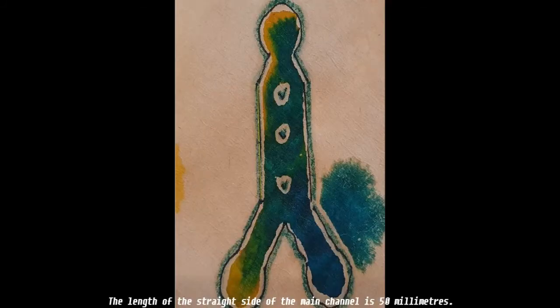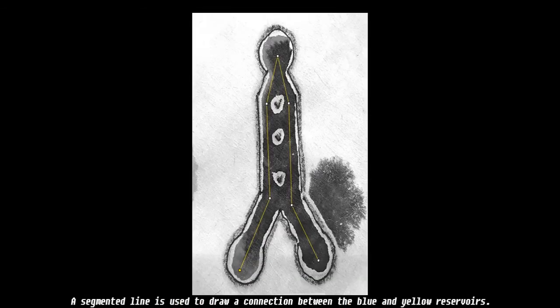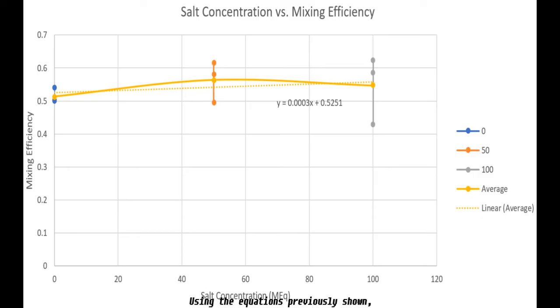The length for the straight side of the main channel is 15 millimeters. A pixel to millimeter scale is set in ImageJ using the yellow line as a measure in each image. A segmented line is used to draw a connection between the blue and yellow reservoirs. The image is converted to 8-bit grayscale and normalized. Then, the intensity of the pixels along the line are taken and stored. Using the equations previously shown, the average mixing efficiency was plotted against the salt concentration.